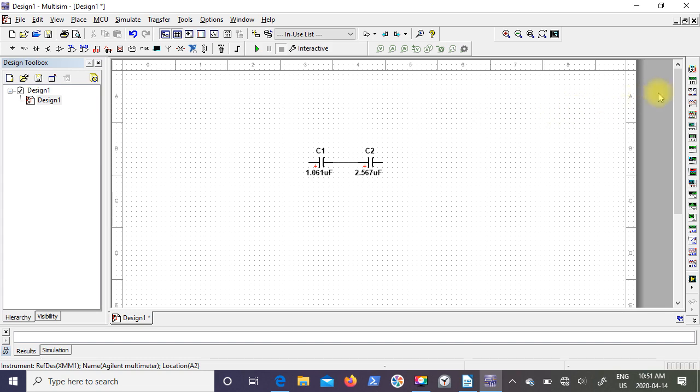So now I'm going to go back to the right hand side of the screen, and the first item is a multimeter. So I'm going to click on that, drag it over. So you can see the positive. I can drag a lead down and over, and when I try and go down, the whole lead drags down with it. So if I just do a left mouse click, that will anchor it so that I can go down and over and make that connection. Then the negative, I can go down, over, and once again I need to anchor it, so do a left mouse click, drag it down and over.